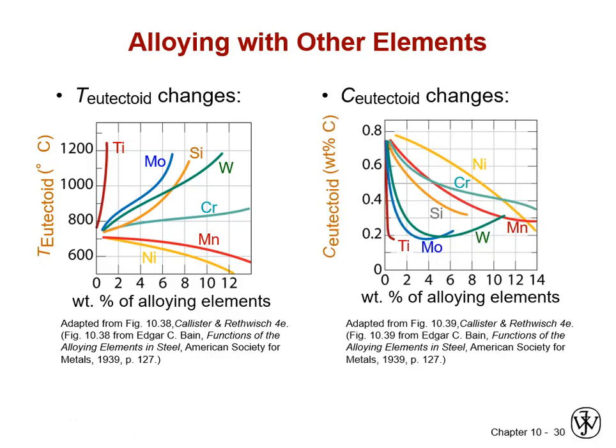And in addition to shifting up and down, when we add alloying elements, we will shift the eutectoid back and forth. In fact, anytime we add another component, any phase boundary, the temperature and composition corresponding to any phase transformation reaction, eutectoid, eutectic, peritectoid, monotectic, there's several of these, all of these will change position because we are effectively changing another state variable. But in the case of steels, the changes are small enough that we don't think of it as a whole different phase diagram. We can just think of it as the same one shifting around.